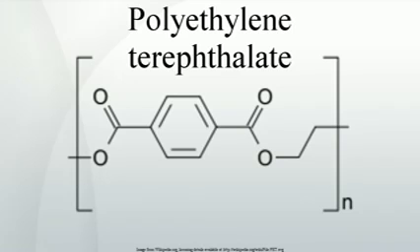PET consists of polymerized units of the monomer ethylene terephthalate, with repeating C10H8O4 units. PET is commonly recycled, and has the number 1 as its recycling symbol. Depending on its processing and thermal history, polyethylene terephthalate may exist both as an amorphous, transparent polymer and as a semi-crystalline polymer. The semi-crystalline material might appear transparent, particle size less than 500 nanometers, or opaque and white, particle size up to a few microns, depending on its crystal structure and particle size.